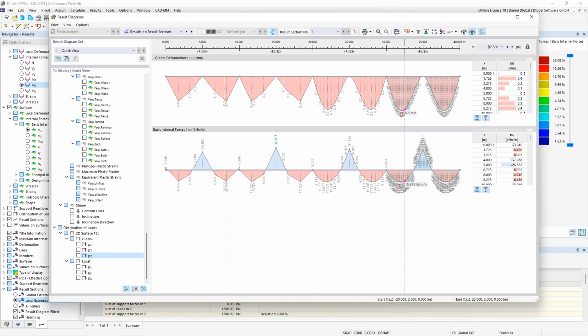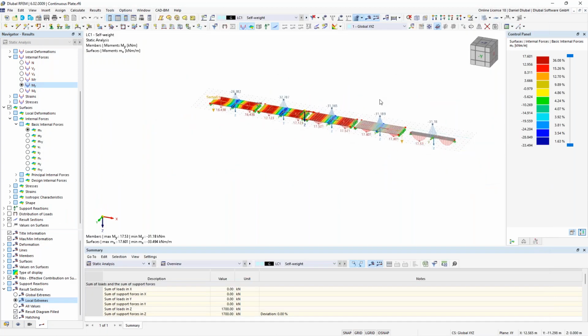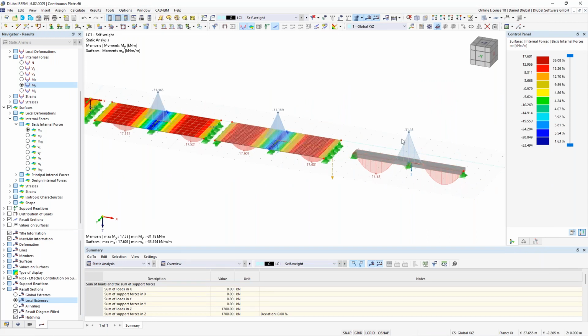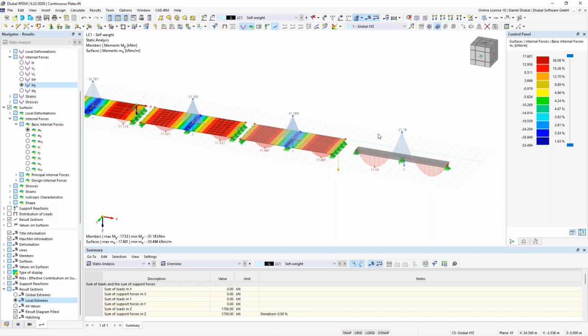Okay, one thing more. Shear stiffness. In order to get here at this beam your hand calculation results, you have to consider also shear stiffness effects. So taking into account shear stiffness leads to an increase in deformation due to shear forces. So these shear deformations, especially at concrete structures, play a major role. So it is recommended to consider the shear stiffness for the deformation analysis.